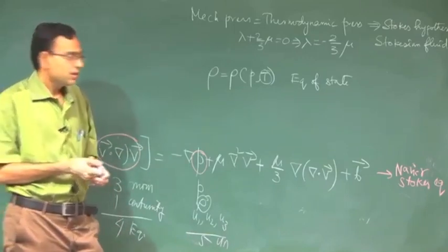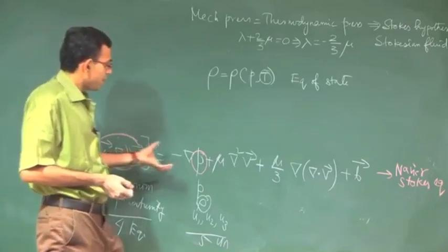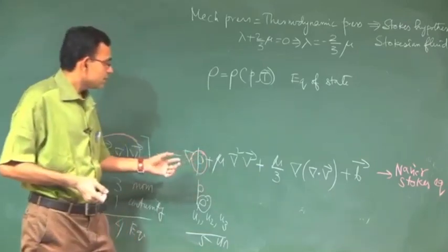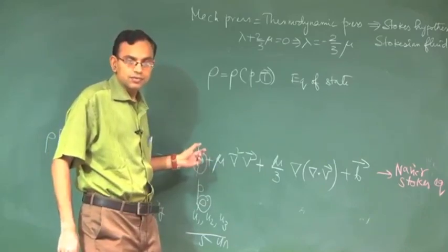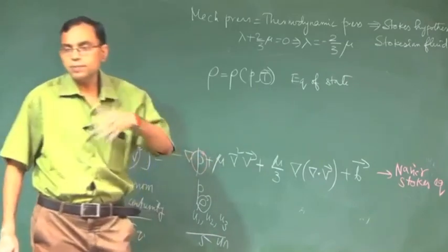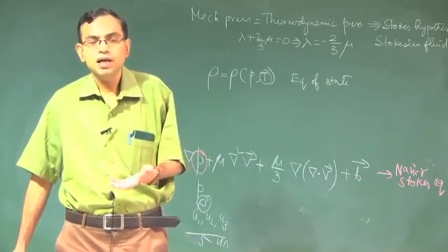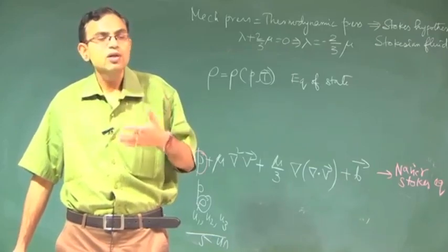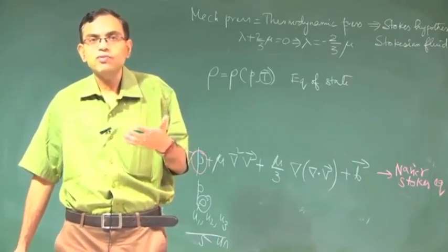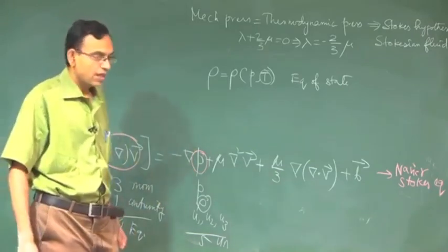So the non-linearity, the coupled nature and the peculiar behavior of pressure, that is, there is no separate governing equation for pressure, but pressure has appeared as a variable, that makes the Navier-Stokes equation so unique and computational fluid dynamics techniques so important.